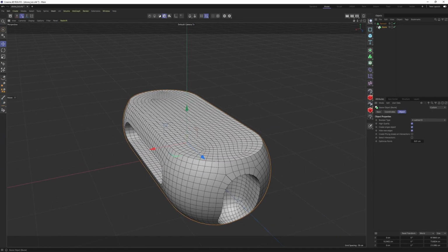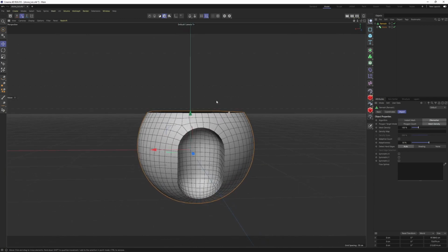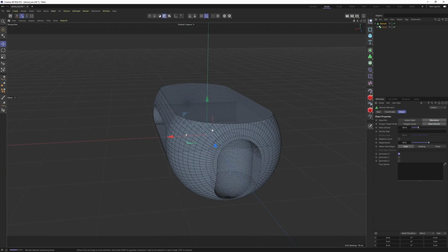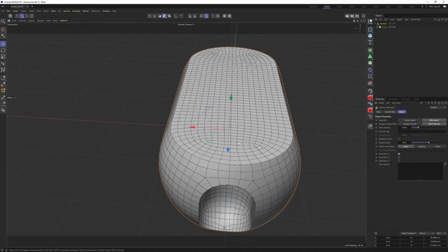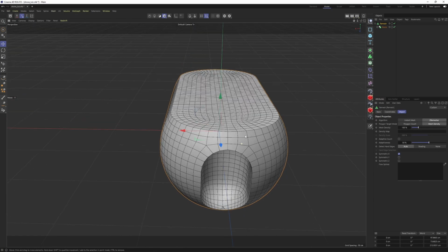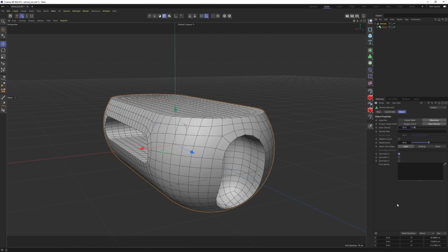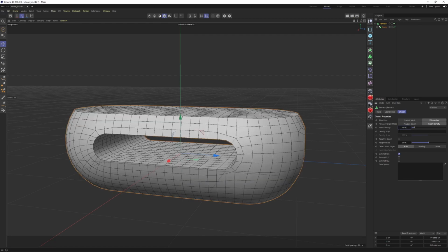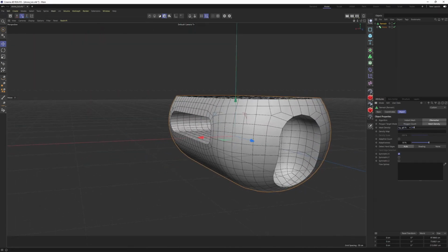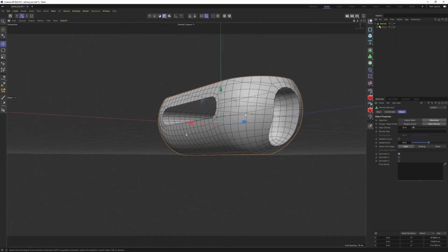Now it's time to play with the Z-Remesher options. Let's come over to the remesh. First thing first, I will enable symmetric X because the object is identical on the sides. And this will also give you that single edge right in the middle, which we can use for symmetries later. Other than that, we can try to lower the mesh density. Right now it is at 100%. Let's make it 50%. Maybe let's try 40. 35. All right, 35 is looking great.